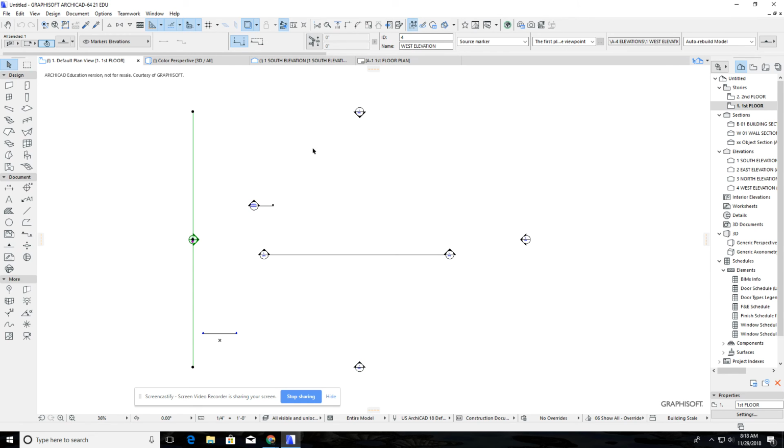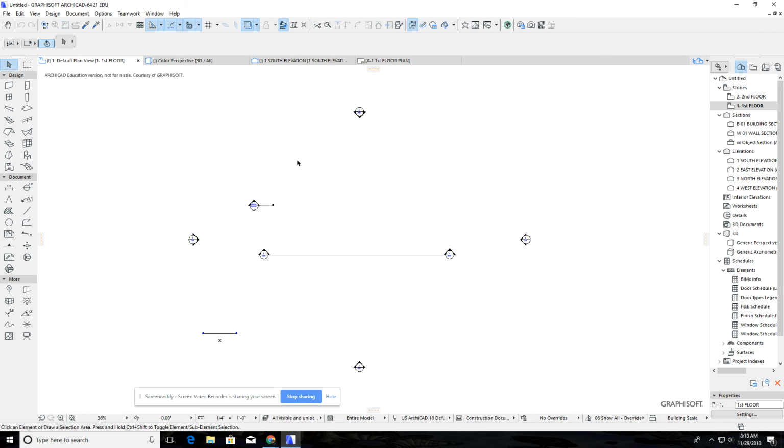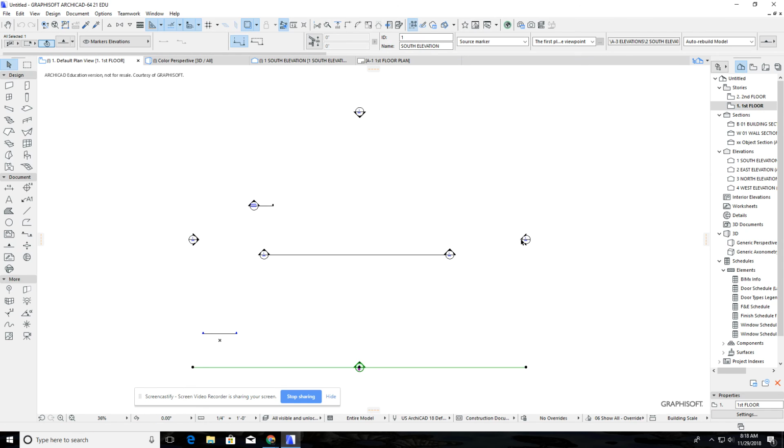Okay. These elevations, whenever you draw a wall, or draw anything, it's going to have an elevation view of that. What you need to know is don't move these, okay, and try to draw everything inside of this. If I go around and press all these and select them, I'm just pressing hold down shift. They kind of create a box. You want everything that you draw inside this box.